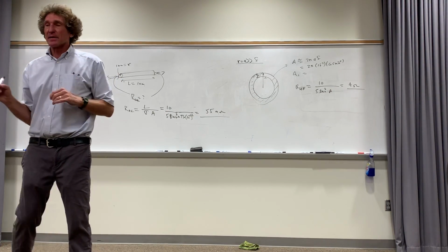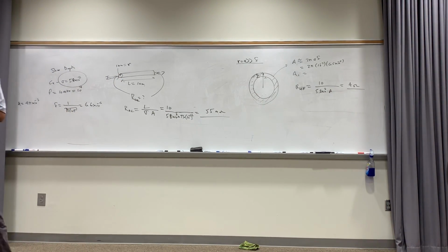And the way to beat that, and that's the way they always do, there's 2 ways. Have you ever noticed, you know what twisted pair cable is? Well, you can find cabling that is individual, very thin strands of copper, wrapped with an insulator, woven like bundles, there are hundreds of them. That will get rid of the skin depth phenomenon. Another way is to have a big wide piece of pipe and just a very thin piece of it.